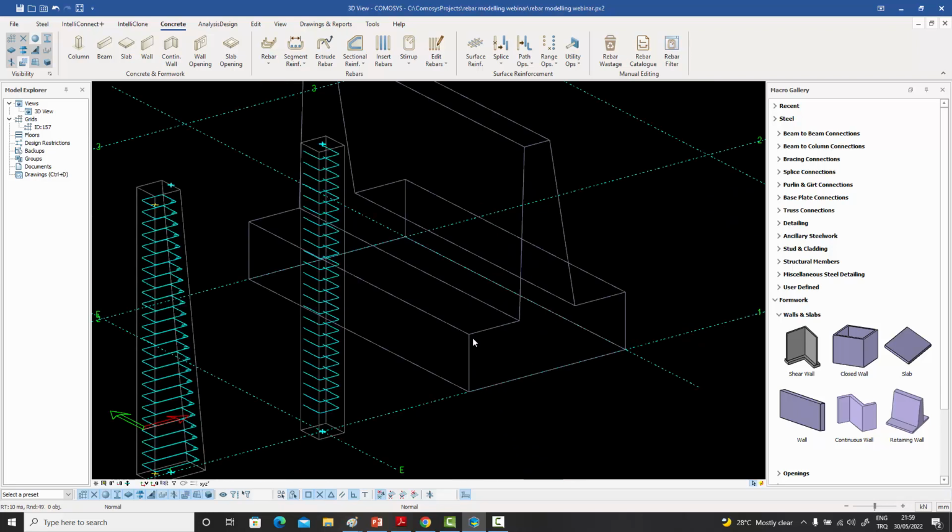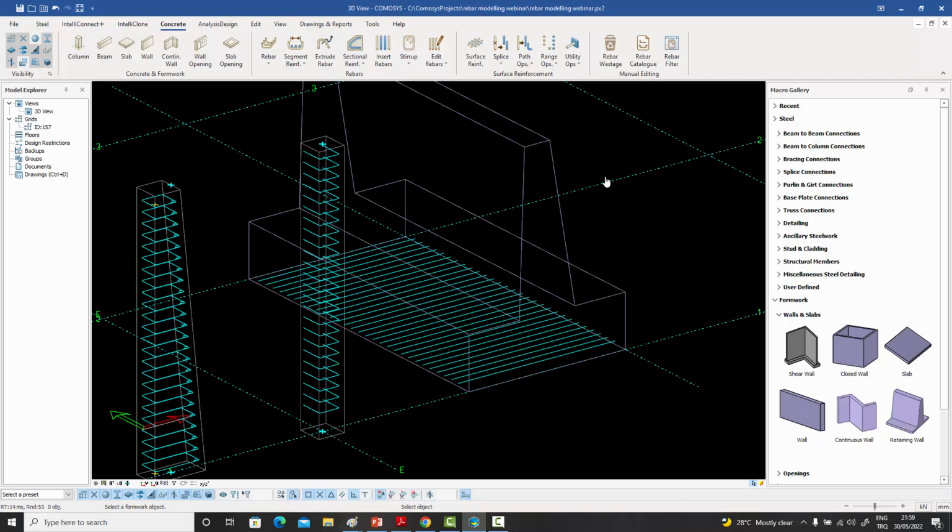Let's move on to a slightly more complicated cross section, like maybe a retaining wall. Once again, go to my sectional command, select that parent, go and select any point on that surface. It immediately gives me the cross section at that point. Let's say I only want this bottom bar and I don't want the whole cross section. I select the bottom bar and press right click. And then I have to go to another point at the end and it brings me the same bar, and I just say right click to create those bars.